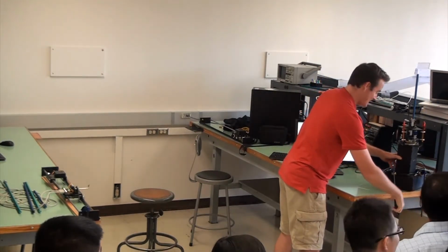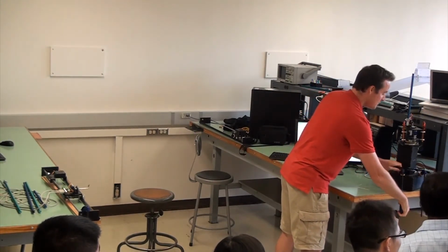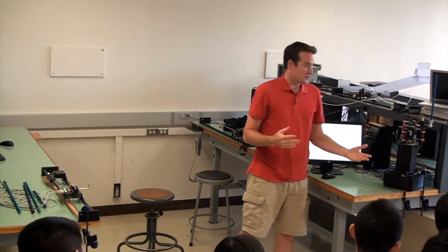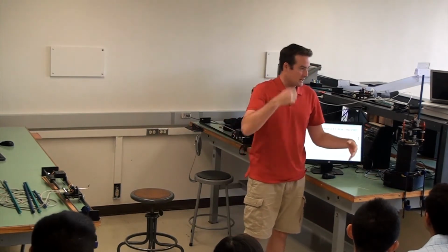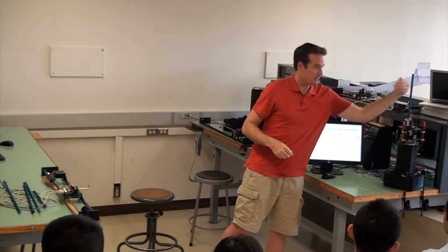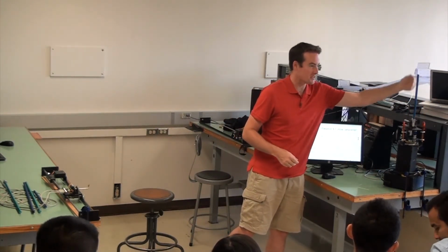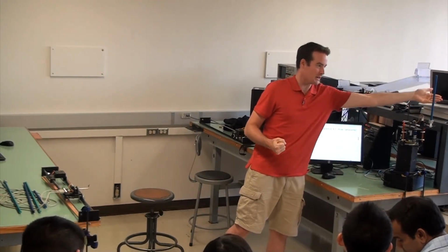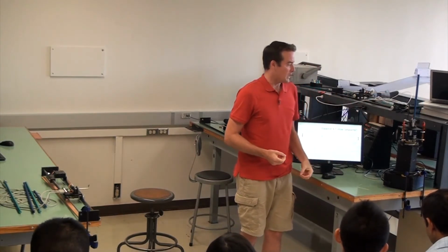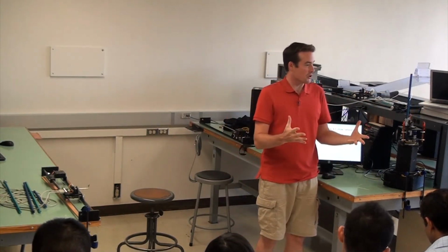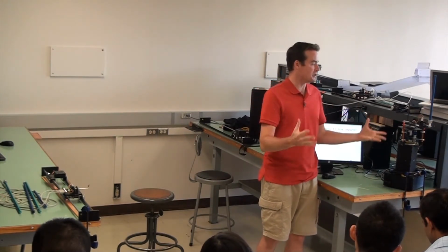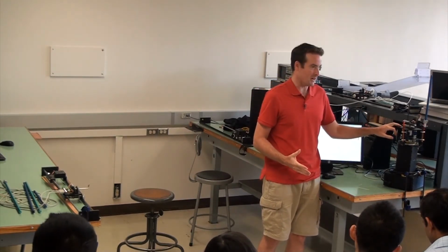What if you change the material, like the material of the rod, for example? Yeah, that will change the mL squared term. That will change the moment of inertia, how fast the rod can tip over. So if you made it out of tungsten or something very dense instead of just aluminum, it would not fall over quite as easily. It would essentially be a different term that you would have in your equations of motion when designing the controller.